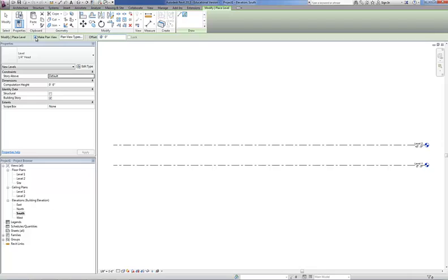You could also have levels that are created within the project, such as top of framing or top of wall or top of structure or foundation, where you might want to establish a height within the project, but you might not have a floor plan view associated with that level. But for all of the ones that we're creating right now at the beginning of the project, we are going to have floor plan views associated with those. So I want floor plan view or Make Plan View checked.